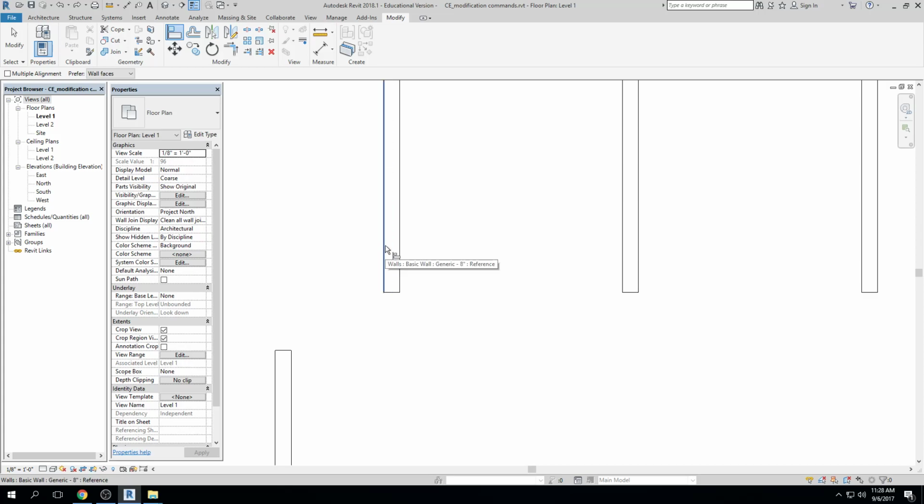If you go too far, sometimes it'll be like no, and it will ding, right? But right now, if I want to go to the middle, I can tab. And now if I click, right, it will select that midpoint for alignment. Okay. Before I do this alignment, I also want to show you one other option, right? Revit is all about the options.